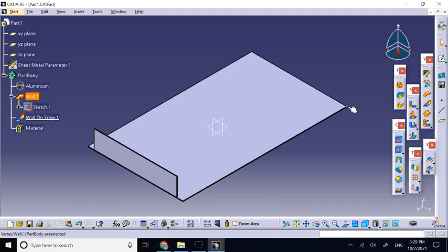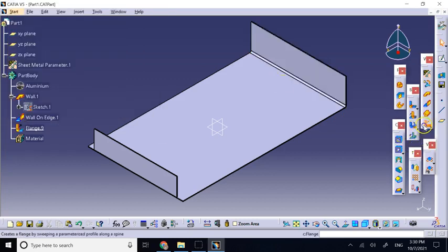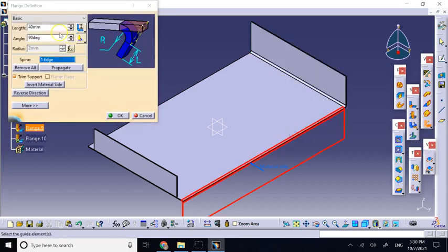And so cutting that sharp point out and, let's say, making it round, or any other cut like the square that we have, but I guess circular is the best one, that releases the stress a little bit at that point and avoids tear. So let me show you that. Here we go and create a flange on this edge, let's say for 20, 40, whatever mil, in reverse the direction. Right, and then I do a similar thing here on this one.